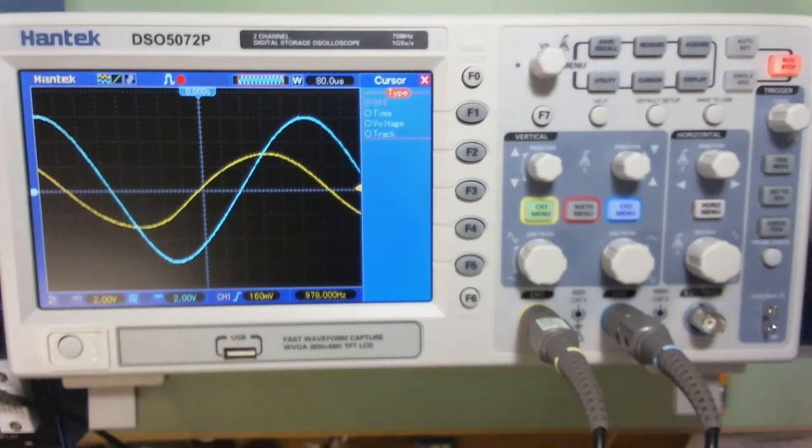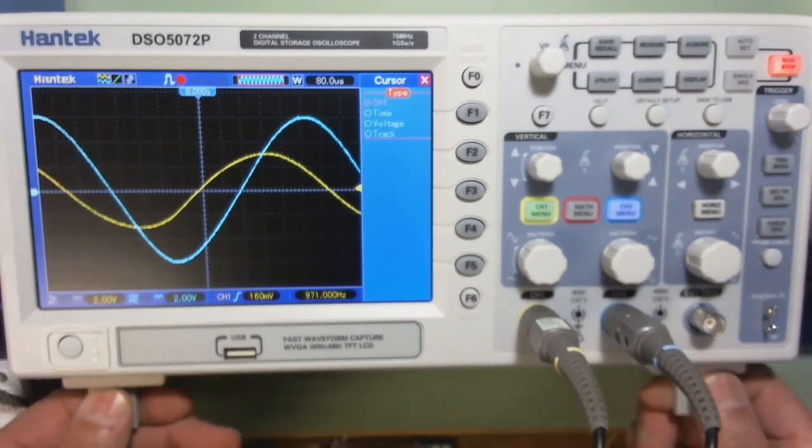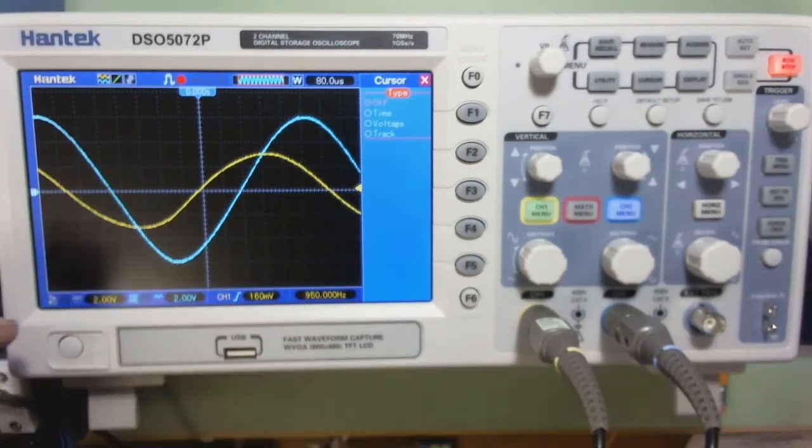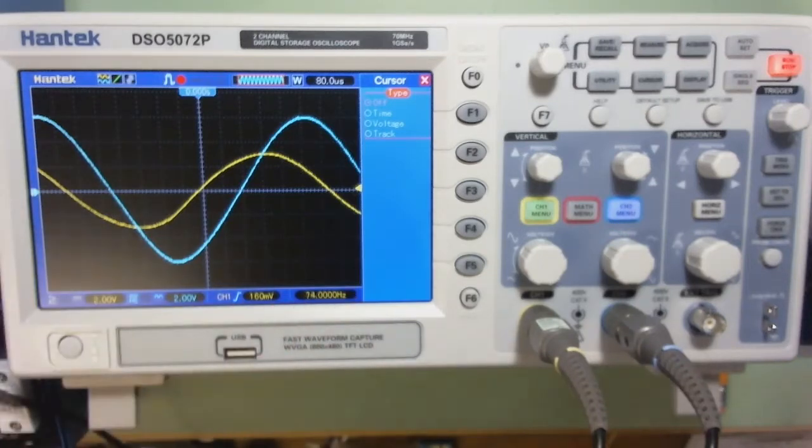For the civil engineers that are finishing up this class and probably glad for that, the oscilloscope is a great measurement tool, and it allows you to measure things in real time. Time on the horizontal, voltage on the vertical, and it's a little more sophisticated than that. You can start to do plotting on here, but about 99% of the measurements you're going to do, time on the horizontal, voltage on the vertical. That's for the mechanicals and the electricals next term. That's what we're going to be doing almost all of the time, and we'll get some more practice with this.